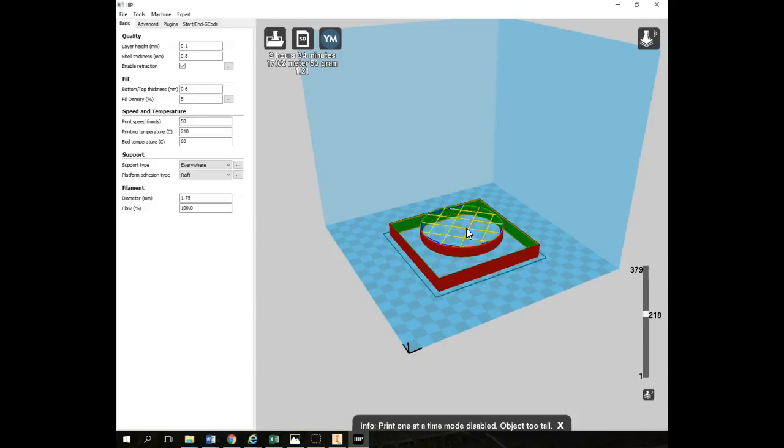That's because when you 3D print things, this program's purpose is called slicing. This is where it takes your object and figures out how to create the object not as a solid object. So this grid work, these lines are literally where the filament would be laid down, because right now the fill density is set to 5%. Now, if I increase that to say 20%, I see it's 9.5 hours and 53 grams of material. Drum roll, please. Now it's almost 14 hours and 90 grams of material.